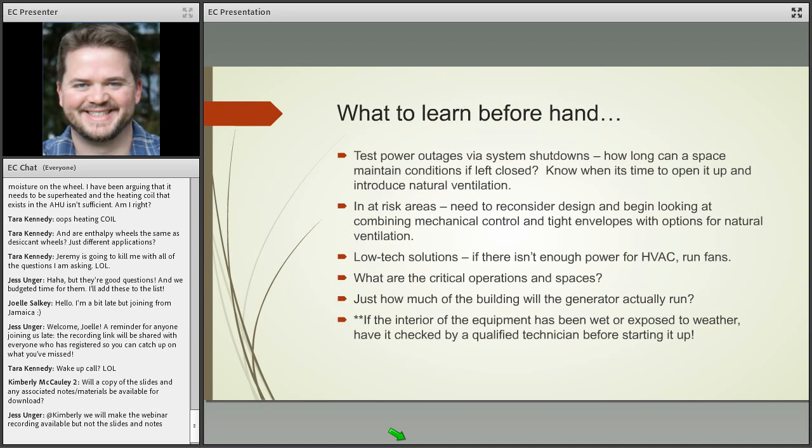But I think when we design that, we have to understand that there needs to be a means of providing natural ventilation when necessary, when these events occur. We can't just rely on the fact that the refrigerator is going to stay closed. Eventually, the outside condition is going to get in, and we need to make sure that we have a way of circulating air through that environment in order to reduce the risk of mold growth, and to at least minimize the overall environmental damage that occurs.